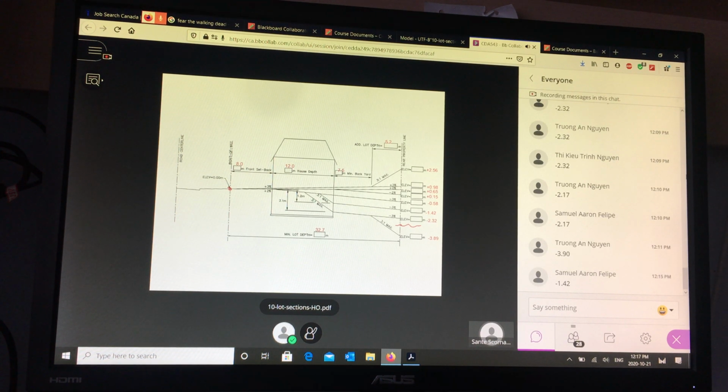Then what I would do is a full walkout. So I would design the elevation at the front, the elevation at the back is a full walkout, and then I would come down at 3% and I would come up at 3-to-1 from this backyard elevation. That's the existing. I would come up at 3-to-1 and I'd have a little extra usable backyard. It's a bad drawing, it should be parallel, but that's what I would do.